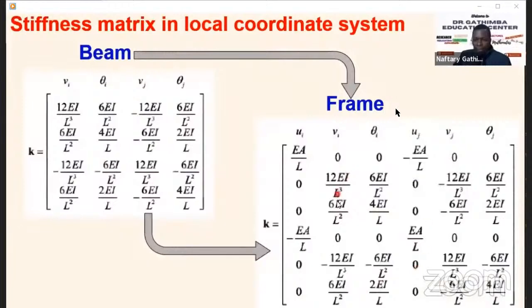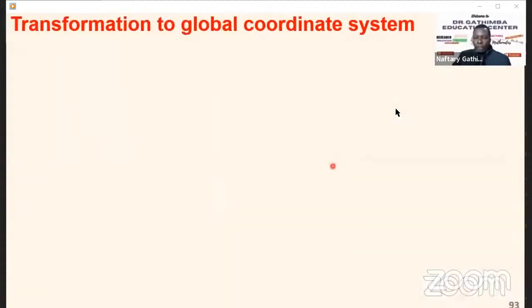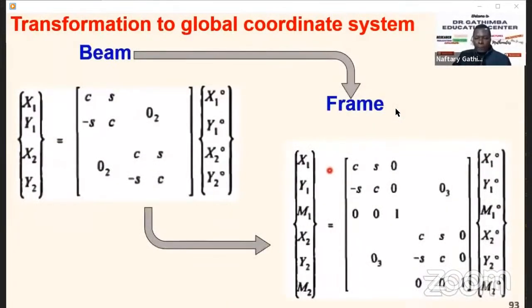So for the beam element, this is a transformation matrix, this one. This is the beam element. Now if we do not have EA over L, of course, we need to augment. EA over L, this already we have combined. By the way, K rod plus K beam is equal to K frame. This is the K frame in the coordinate system. So you can just pre-multiply this.